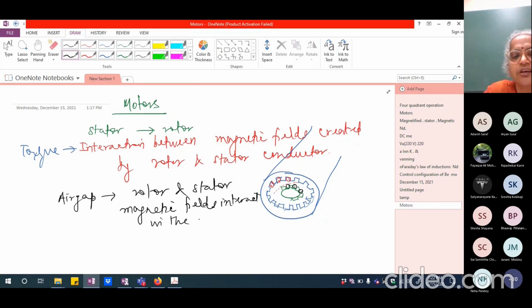So what I'm trying to get at is that although we say literally through air the current carried may be zero unless you create an electric field strength to the tune of 30 kilovolts per centimeter. You have to apply really, really large voltage so that the air gets ionized. Until then, the air is going to be an insulator as far as the electric current is concerned.